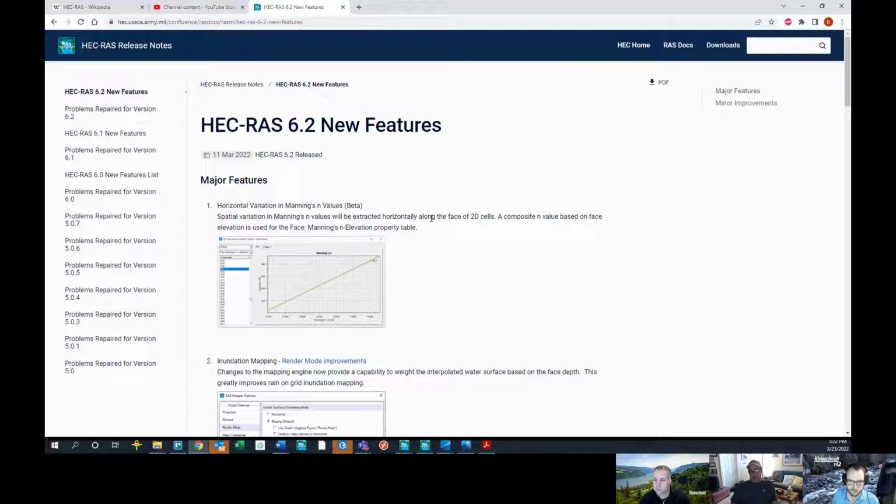So one thing in my new job, I've been doing a lot of work in hurricane modeling. We're working down in the Louisiana Water Initiative project, and in RAS we added wind forces, but we're still using combined ADCIRC for coastal and RAS for the boundary, taking ADCIRC boundary conditions and coming inland with that. But I think HEC needs to add pressure force differential for hurricanes into RAS, and that would be an easy thing to do. And I think they actually are going to work on that. And then probably later on, well down the road, look at adding forces due to waves.